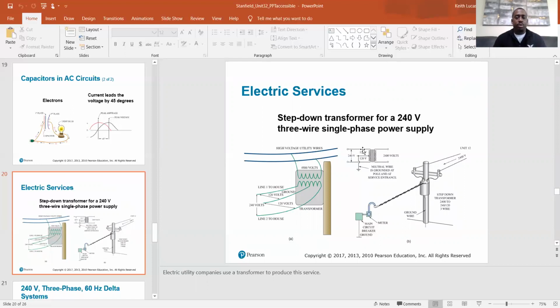Then you have your condenser fan motor outside by your compressor, and then the compressor itself is a motor. Those are high voltage motors. Those run off of 240. Then even if it's gas heat, you got a 4th motor. You got your induced draft motor, which is in your furnace, also a 120 volt motor. But then you got your thermostat that controls it all. Now your thermostat doesn't need 120 volts to open and close tiny little circuits on the little circuit board that's on there, because your thermostat basically is a circuit board.